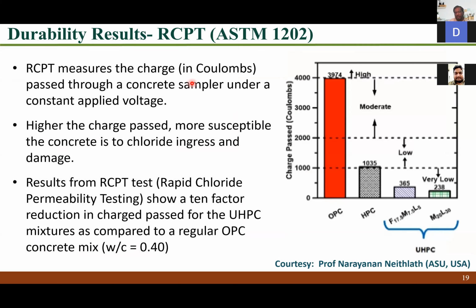Right. So like I said, we talked about strength and flowability. Of course, we need to do the slump cone test when you're developing a mix design, so we need to make sure they're satisfied. In addition to that, durability is also an important parameter.